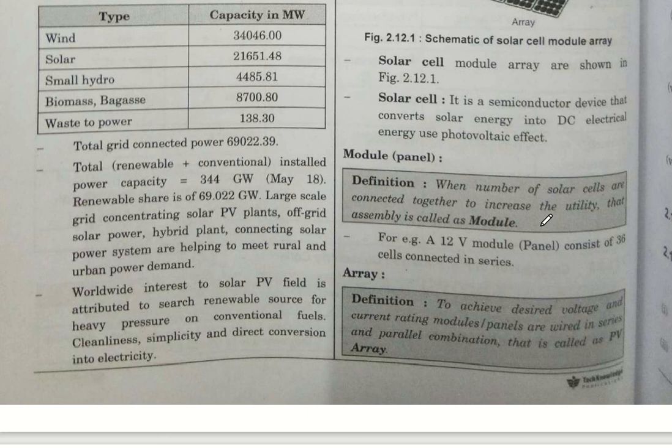Okay, and we have seen previously how many volts one solar cell can produce. Does anyone remember that? Around 0.5 to 1 volt. Okay, so here we are producing 12 volts and we have 36 cells connected in series. Now what is a solar array?